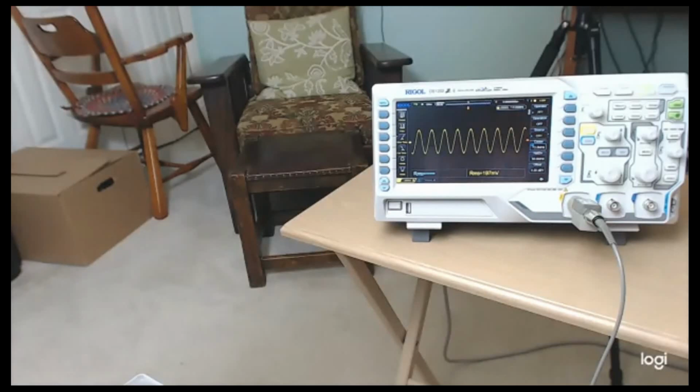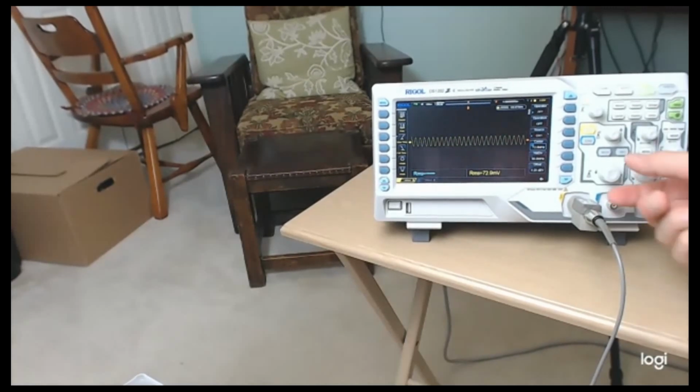What's the upper frequency limit? 62.5 megahertz. As you get above about 40, the quality of the sine wave tends to drop off a little. Let me pump it up a little bit and see. That's at 7. And you can see what's happening is as you get a higher frequency, you don't have as much amplitude. So the strength drops off. It's the filter you have to stick on the output of that thing to make a sine wave. It tends to roll off.